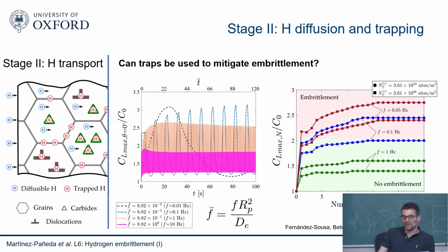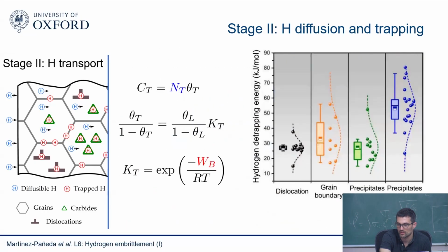So it's a big discussion, and of course it matters whether it's semi-coherent or coherent. They also report different binding energies. I think you have it here. So you have precipitates with coherent interfaces, with semi-coherent interfaces, different binding energies. Ideally, what people have tried is vanadium carbides in chromium-molybdenum steel. I'm trying to remember, I think there has been something else. Harry Bhadeshia in Cambridge has done quite a lot of work on this, very nice work. I think it has been mostly vanadium, because then they can control them. They can also be at nanometer scale, very small. But all of those things are important.